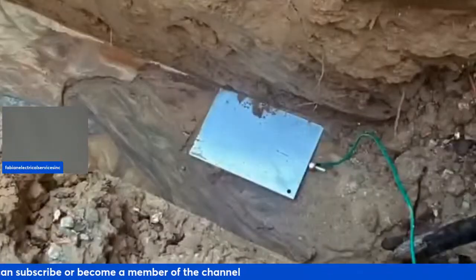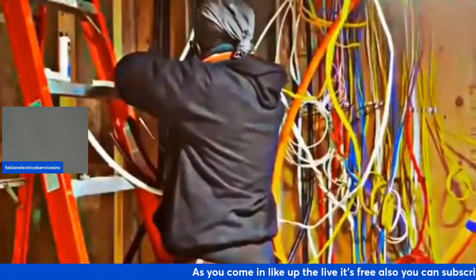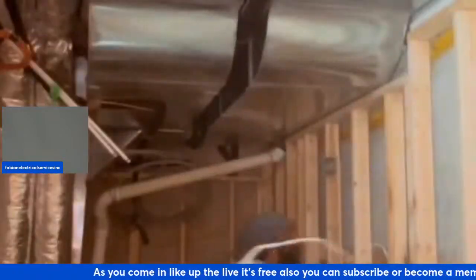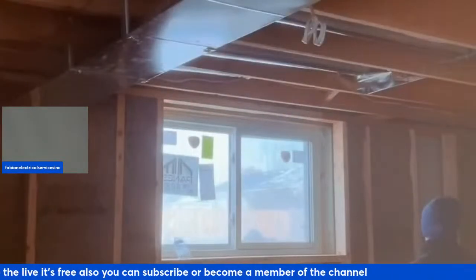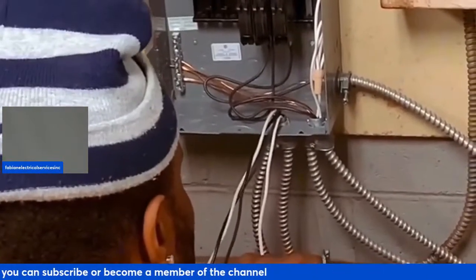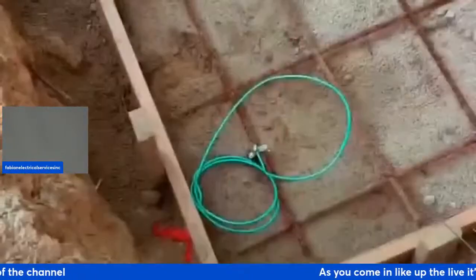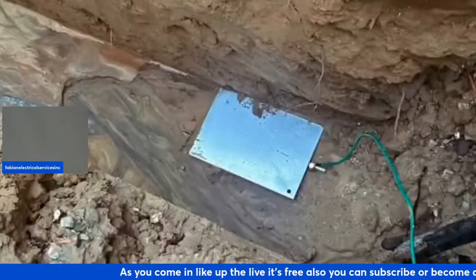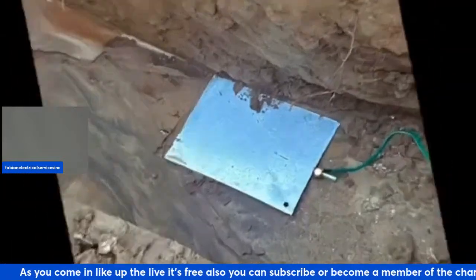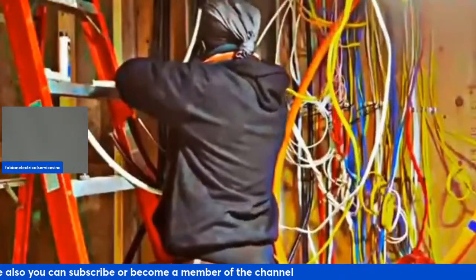And again, why GFCI outlets are important. They prevent electrocution and severe electrical shocks by quickly interrupting the flow of electricity. They can also prevent fires and reduce the severity of fires by interrupting the current during a ground fault. They are crucial safety features in areas where electrical devices are used near water, such as kitchens, bathrooms, laundry rooms, garages, and outdoors. Outdoors, you're going to find them protecting the outdoor circuit.